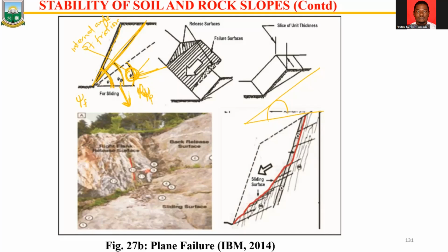And we said that for us to avoid this type of failure, one of the things we needed to have done was to reduce this angle. So assuming this one is 60, this one was 30, and assuming this is 45 or even 50, it means that to avoid the planar failure here, our angle should have been somewhere around 45 or 49.